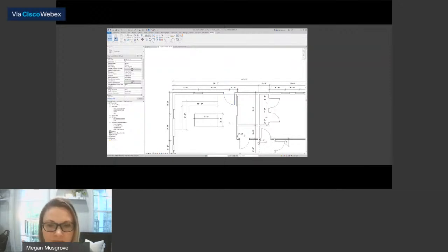Depending on how many people you have cooking in your kitchen, if you've got a lot of people cooking in there, you might want that to be 4 feet. If you're looking at accessibility and you need room for maneuvering, you know, walkers, wheelchairs, anything like that, you might want that to be more. I've got a galley kitchen that I'm doing right now in a home, and a galley kitchen just has a run of cabinetry on each side. It's a kind of a long rectangle, and we've got all our functions hugging these 2 outer walls, and there's about 7 feet of space in between those runs of cabinetry, and that sounds like it's a lot.